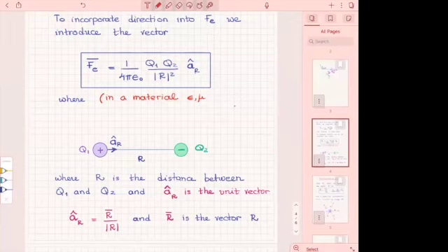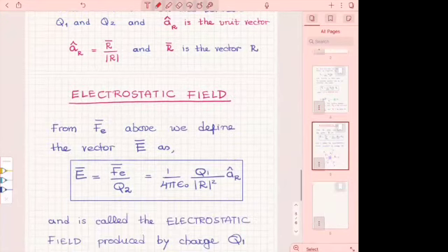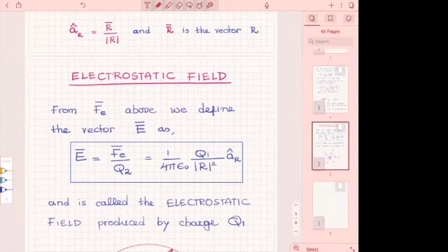So what happens? There is a very strong electric field, as you will see later, because of the electrostatic force, between the cloud and the ground. And then what do we have? Dielectric, air breakdown. The material under this very strong electric field becomes ionized and practically becomes like a conductor.